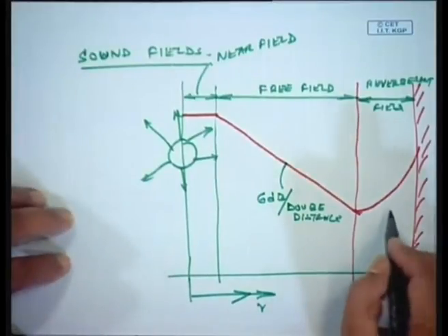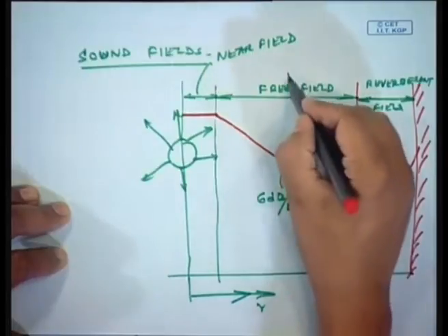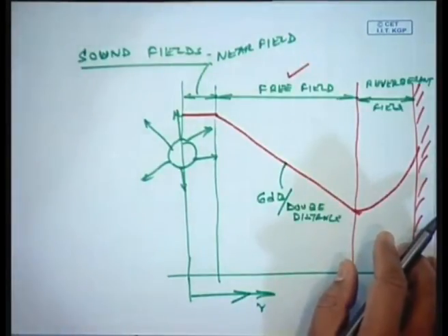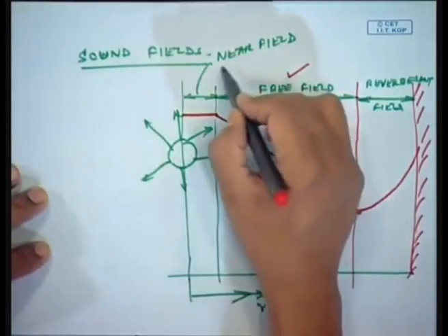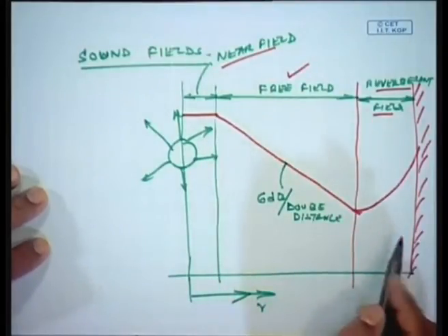Okay. And so, always a good area to measure, as I was telling you, is the free field measurements. So, in noise monitoring, when you say distance from the source, you can also say whether it is in free field or far field. So, always avoid near field and always avoid reverberant field.